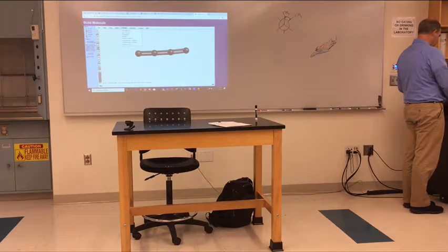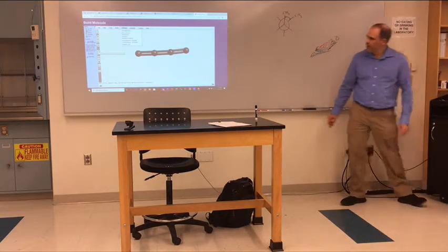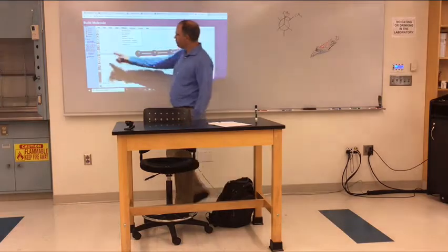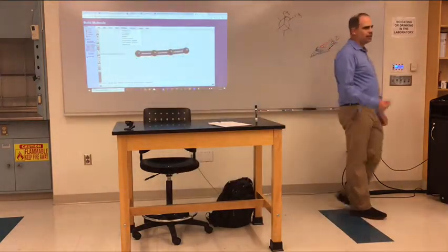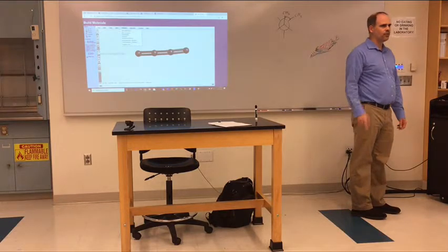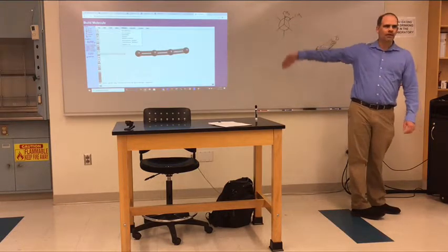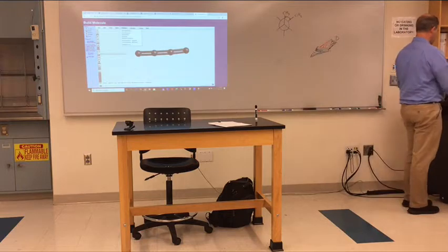You can also, over here on the far left, there's a thing that looks like a broom and a thing that looks like a wrench. Those are icons that do the idealize and the mechanics optimizations as well. So you don't necessarily have to go up to the cleanup and the drop down. You can do them from there as well.